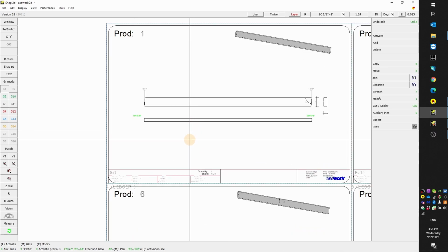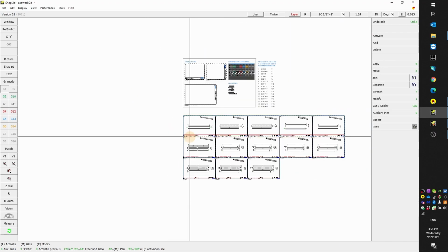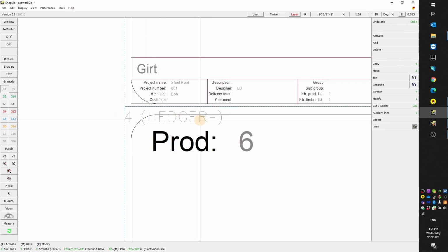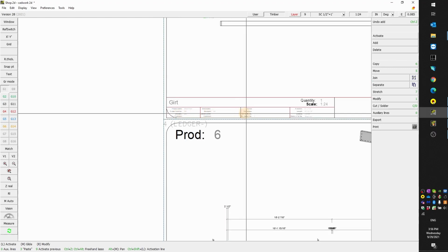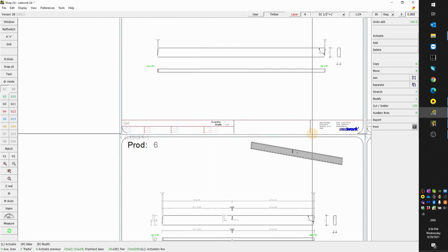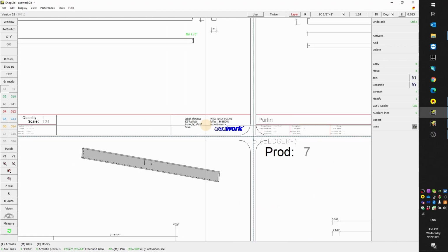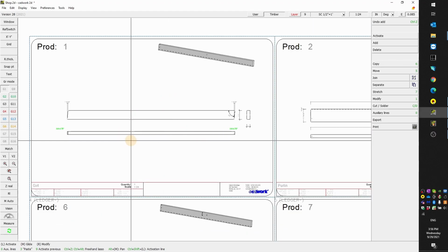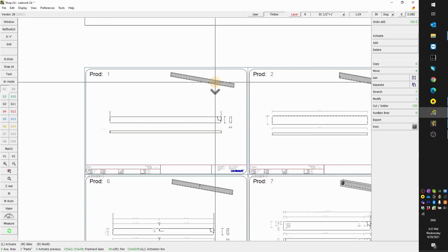Otherwise, they are grayed out. Here you see that's part number one, part number two, three, and each part is on an 11 by 17 ledger page. The title block is filling automatically. I have the title block also with the logo, with the company info, different views of the parts, so that it can be customized, and I have an axonometric view as well.